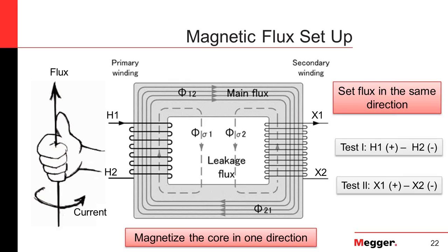When we perform winding resistance testing, we cannot use AC, we have to use DC, because otherwise we're getting the impedance of the winding, and that's bad. We're seeing the impedance, we are not seeing the R, the resistance. The only way to measure resistance is by applying DC current and then letting that core saturate so that all of the inductive effects of impedance are removed and we're left with only R. Hopefully that is sufficient for the question. If not, we'll find out.